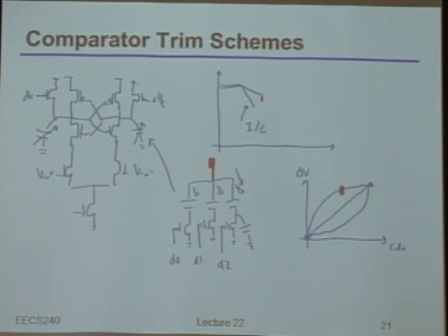There's probably something similar you could do, where you'd, for example, tie the capacitors in a bridge across here. But at the end of the day, it's still the same basic idea in that you either want that capacitor to have an effect on the output or not. And any which way you do that, there's always going to be some extra parasitic capacitance that you can't get rid of that will load the output of this comparator. That's really the fundamental issue.